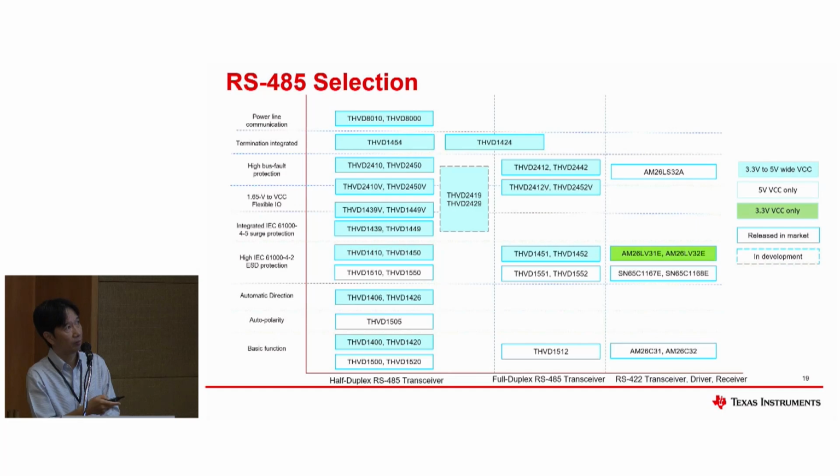For example, if your existing system has a 5 volts power supply, you can just look for the 5 volts transceiver for your design.